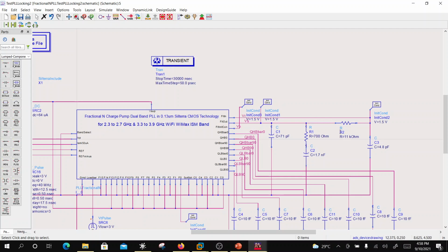and R2. And this loop filter is a third order loop filter, right? You can see what is establishing the order, the RCs. So there is a combination of RCs. Basically there are two C's and an R, so that will establish two poles. And then there is another R, so with that there will be another RC time constant. So basically 3 RC time constants, and then there are going to be 3 poles. So this is a third order loop filter. Okay, there is a final capacitor here also. So basically there are 3 significant poles, and this is a third order loop filter, right?